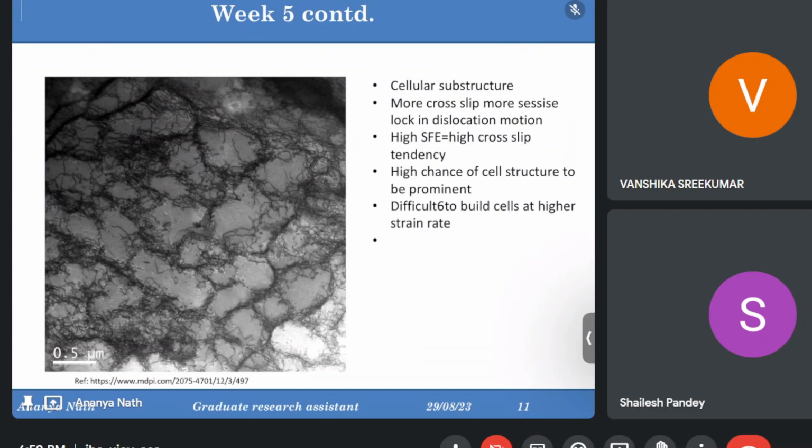So what happens is the dislocation density is so high that they pile up, and now they have gained a cellular structure. What was taught in the class is that inside the lattice the dislocation density is so high that they pile up like this and try to make some cellular structure so that they can have a low energy gradient and low energy configuration.